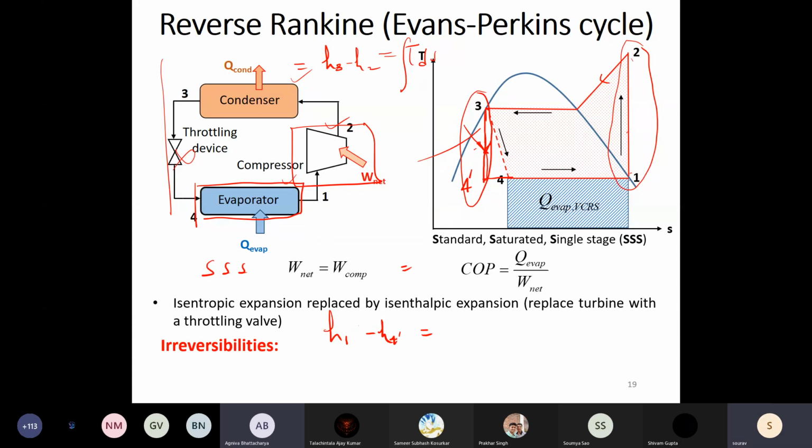Now for obtaining that 20 watts, you are placing another device, a device which will be very similar to your compressor, which will also require some maintenance, or it will also incur some capital investment. So it doesn't make sense in such small systems to place an expansion device which produces work. So that's why we replace it with a throttling device, because all we need to do is drop the pressure from this to this. Dropping pressure is not an issue.